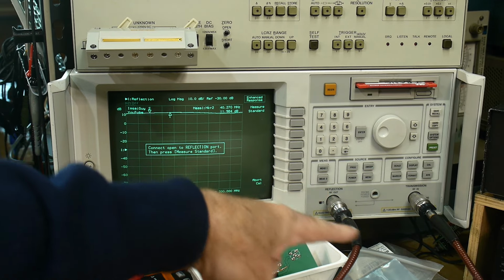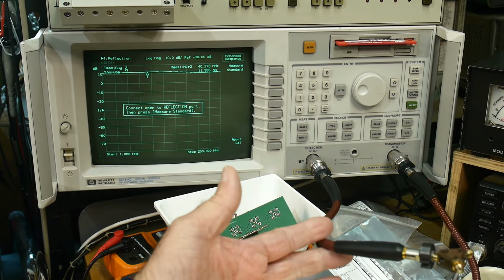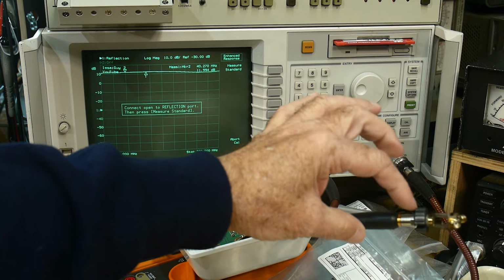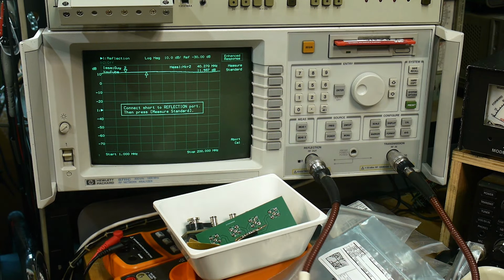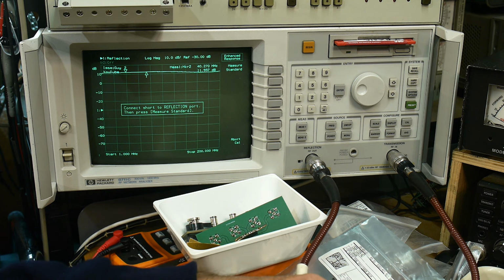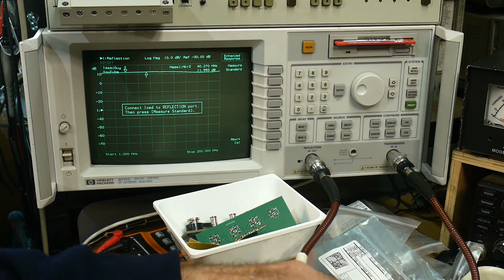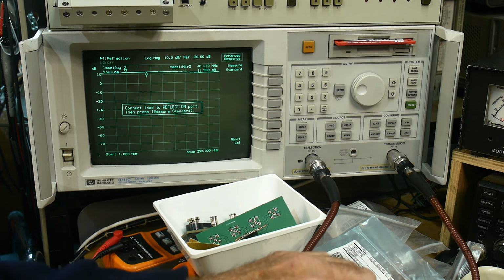Well, this is the reflection port. This measures S11. We're going to be measuring things at the end of a cable, so we need to calibrate at the end of the cable. So I'm going to use my cal standard, and I'm going to cal right here at the end, okay? So that's the open. And we will do the short. I'm caling between 1 megahertz and 200 megahertz, and that's just for convenience. It makes the graphs look nicer, so we'll go up to 200 megahertz. And we'll do a load.